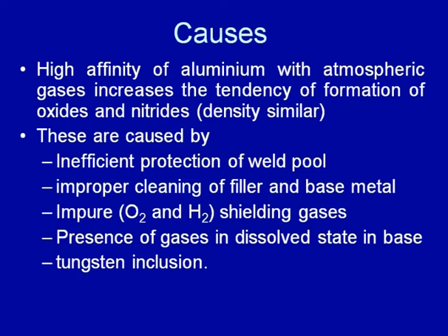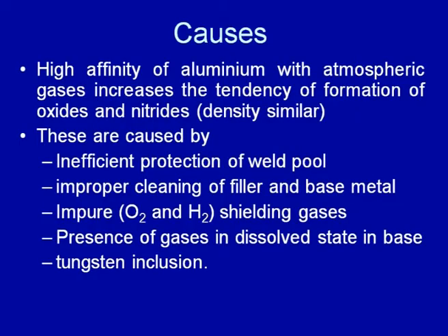Whatever the method being used to protect the weld pool, whether it is vacuum in case of electron beam welding, or the shielding gas not being used in the amount it should be, meaning the gas flow rate is limited or excessive, and the movement of the arc during the welding. All the factors that affect the protection of the weld pool will increase the possibility of inclusions, and so will improper cleaning of the filler material and the base material.